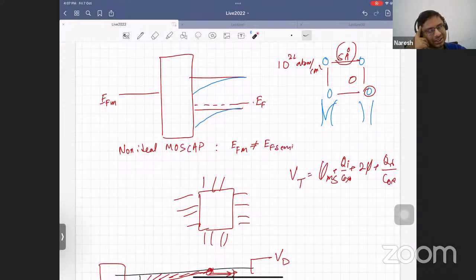Actually, I think in the early 60s and the late 50s, NMOS devices were more prominent. PMOS was actually much harder to achieve. So they built what is known as the NMOS inverter and so on. Even the Intel 4004 processor, I think, is mostly NMOS. It's not CMOS. The other reason was that you have to match the threshold voltage and all. It becomes increasingly complex. It took some time for them to figure out how to do that.